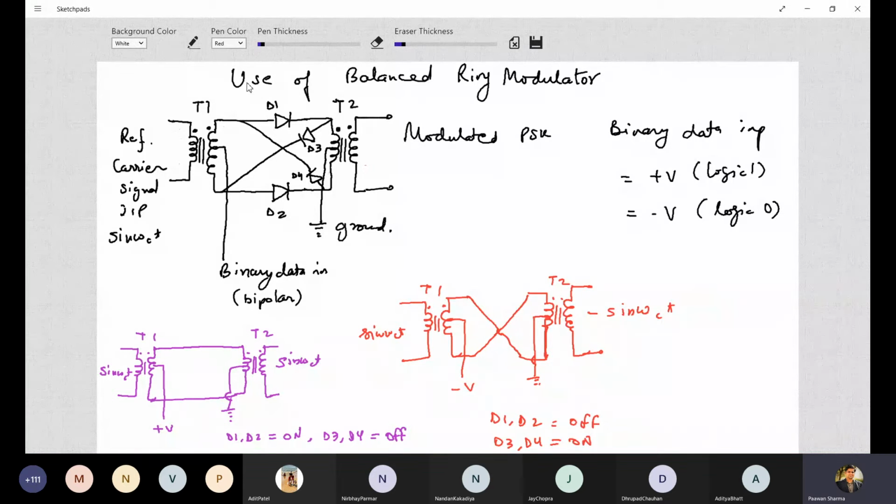So essentially, we are trying to modulate the phase of this carrier signal, right? By the definition of modulation, what do we say? Modulation is the process in which we vary some characteristics of the carrier signal. Now our carrier is sin omega ct, and in phase shift keying we are modulating what? Phase. So this is the first case of phase shift keying, which is binary phase shift keying. And how many phases do we have? M equal to 2. So how have we selected those phases? Totally reverse phases. One will be 180 degrees out of phase with the other, or one will be the negative of the carrier. So if you are feeding sin omega ct, the reverse of this is minus sin omega ct, isn't it? Yes, sir. Because sin(pi plus theta) is minus sin theta.